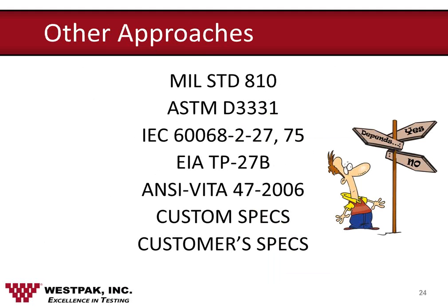It's important to note that there are a number of methods for determining the fragility of products. I dwelled on the damage boundary, but I've used all these methods at one time or another, and some are okay and some are not okay. I've never seen a better procedure for fragility assessment than the damage boundary test procedure just described. While there are some significant problems with the damage boundary procedure as presented, it is far and away the best procedure that exists today for the purpose of determining product fragility and product reliability analysis as well. Highly recommended.